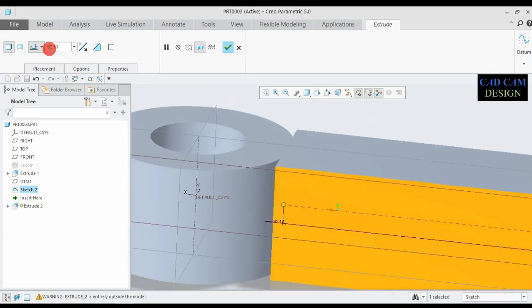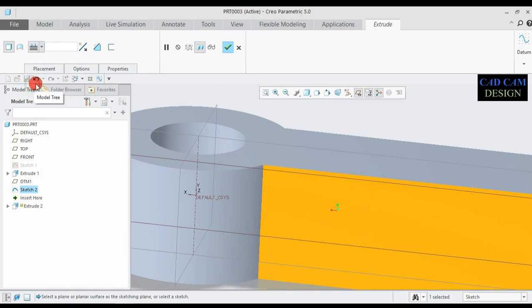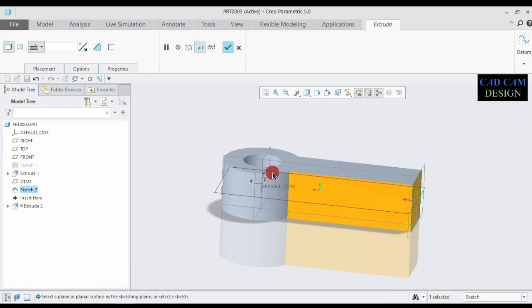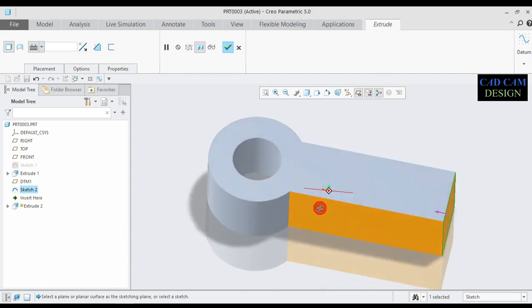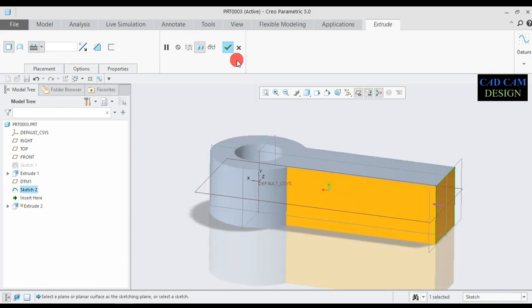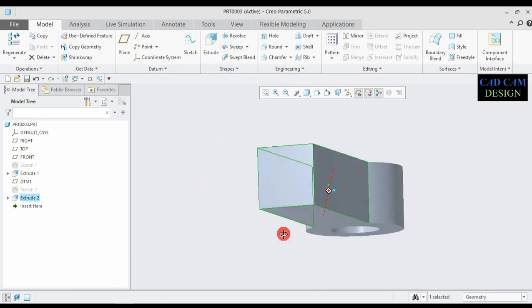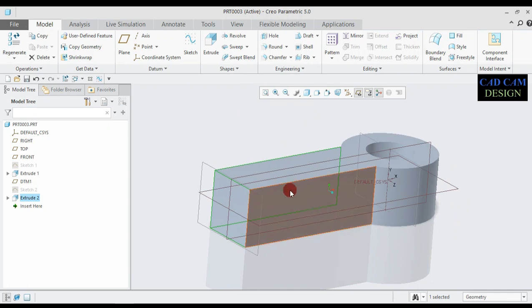This is an error. Now we go to this and select extrude up to next surface, and show our first entity and our second rectangle entity, extruded to the same merge surface result, as shown in this slide, and click done. Now see our half of the second part is done.